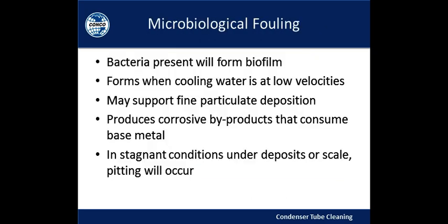Now, in other conditions, microbiological fouling might be your experience. Basically, that's bacteria forming a biofilm. This forms typically when cooling water is at low velocities, and it will support fine deposition, particulate deposition.